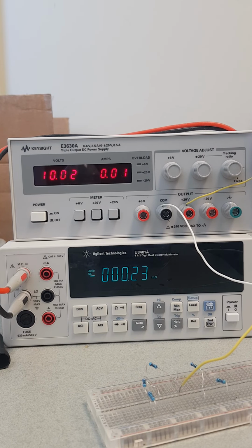So in conclusion, you have to know what phenomenon you are measuring. If you are measuring something that changes a little bit, then you have to make sure that the tolerance in the component is very, very small. However, if the change in the resistance you are measuring is relatively high, then you don't need to pay that much attention to the tolerance problem.